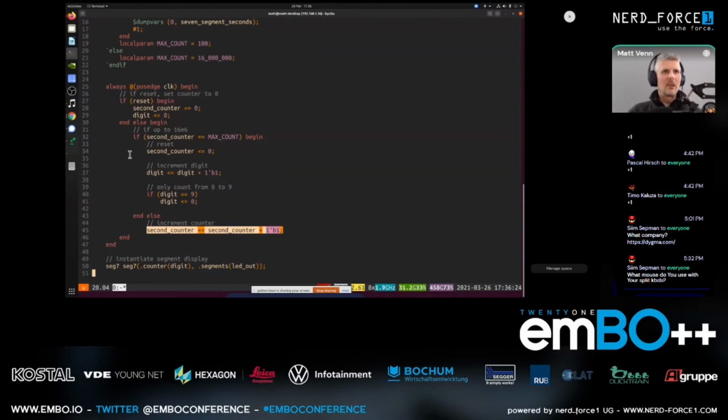And then here I've got a digit counter, and that uses a 4-bit full adder to be able to count up to 9 on the digits. So unlike on a CPU where you have an ALU and you can just reuse it, with firmware using the ALU over and over again, I've got in hardware these 2 separate counters that are completely separate and parallel. And that is one of the great advantages of a custom digital design: you can design the exact hardware you need for a specific task, and then it runs extremely reliably and with very accurate timing and with huge parallelism.